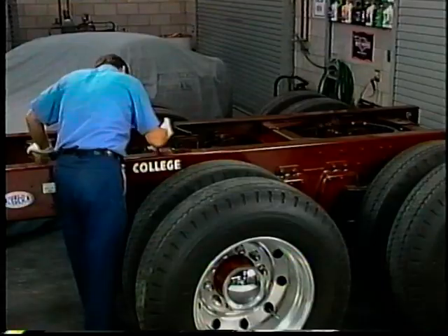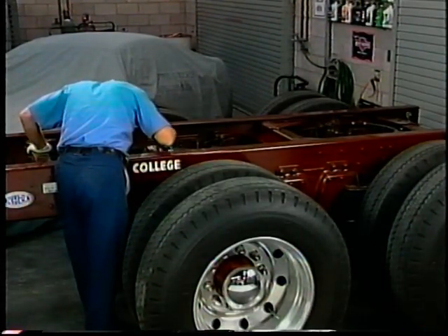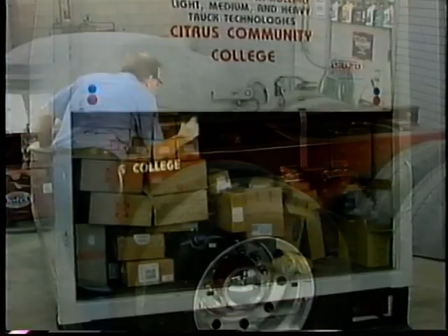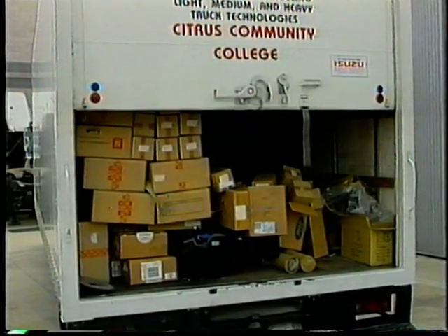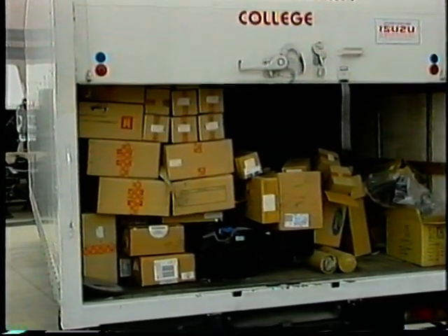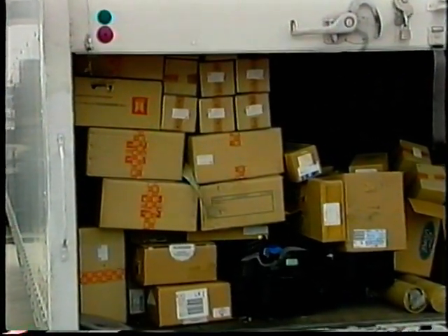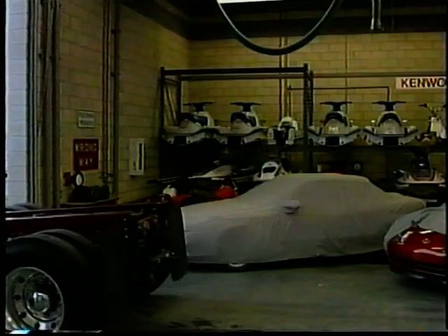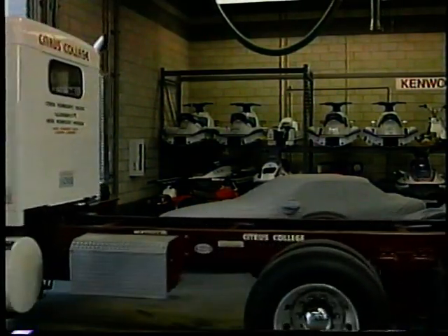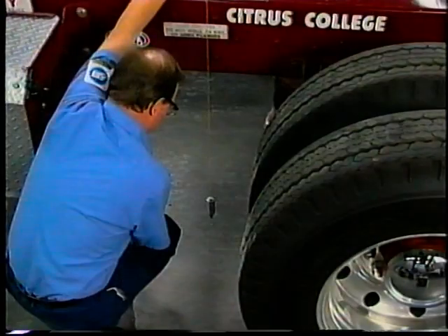The truck frame is subjected to great stress from loads. The most common types of frame damage are sags, twists, and buckles. Frame cracks or sagging is usually caused by overloading, uneven weight distribution, or a frame weakened by incorrect modification by body manufacturers, or collision. Other frame conditions are usually caused by collision or by improperly towing the vehicle, or towing something improperly with the vehicle.